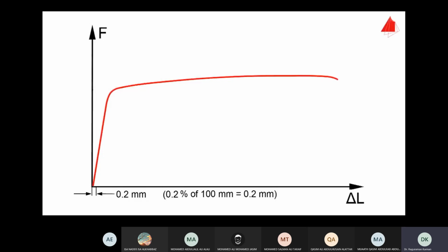In the force elongation diagram, a straight line parallel to the elastic line is drawn through the offset point of 0.2 mm of elongation. The force at the intersection point of the offset line with the force elongation diagram is designated as Fp 0.2. This is the force that causes a plastic strain of 0.2%. The 0.2% proof strength Rp 0.2 is equal to Fp 0.2 divided by the original cross-sectional area S0. Tensile strength, percentage elongation after fracture, and percentage reduction of area are calculated in the same way as in the first test.